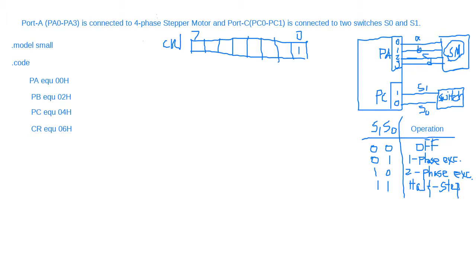Port C lower 0 and 1 bits are part of port C 0 to 3, so it is input. Then port B unused, mode 0, then port C upper don't care, port A as output, and these 2 bits are for mode 0 0, and this is 1.